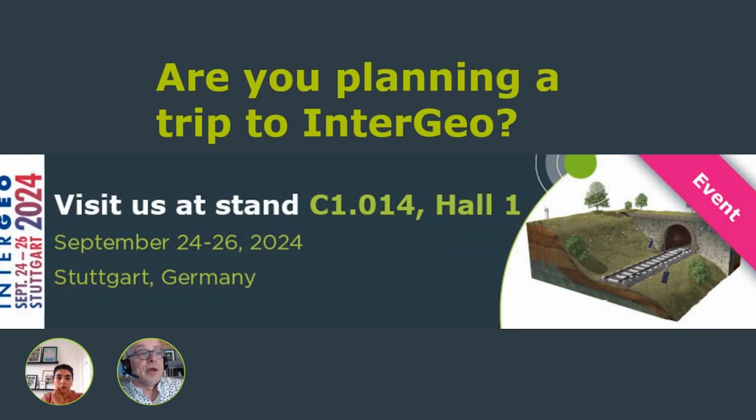When you read data out directly onto your own platform without going through our web monitor platform, all additional calculation has to be done on that computer. You just get a vibrating wire frequency and a sensor temperature, and then you have to do the appropriate calculations to get strain, for example.